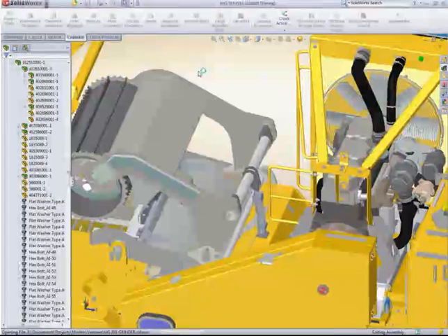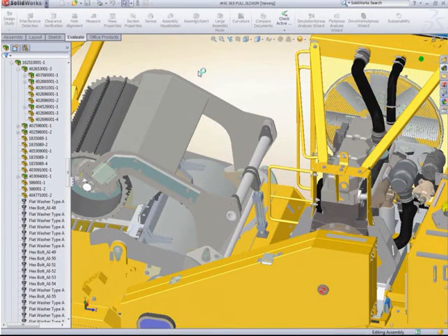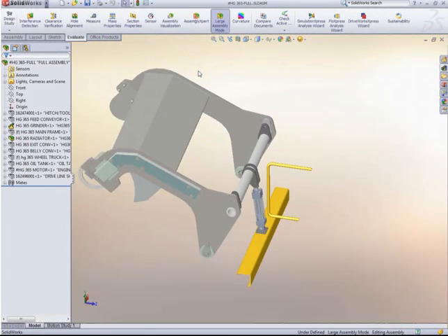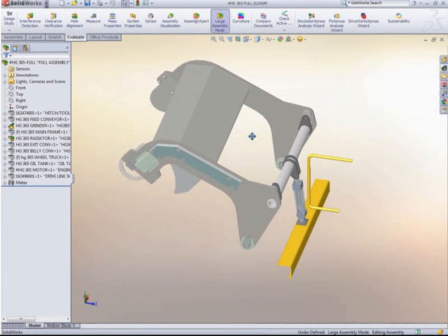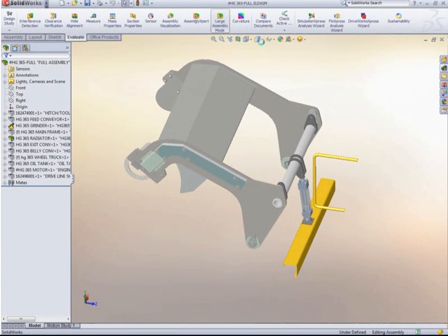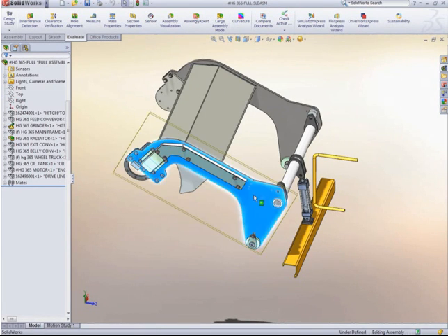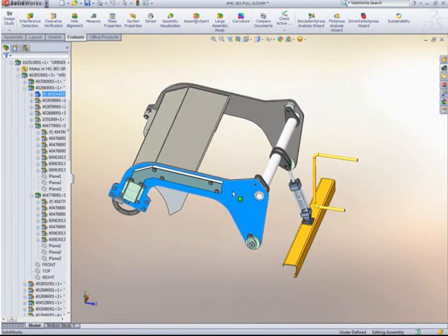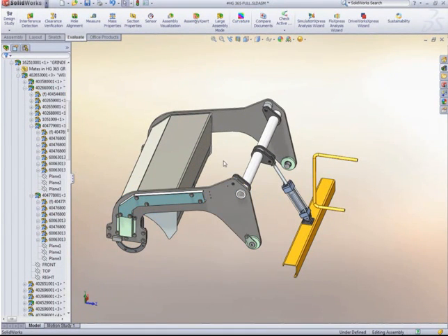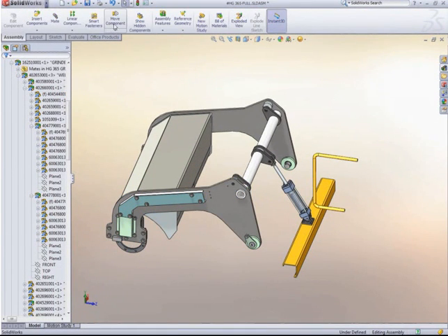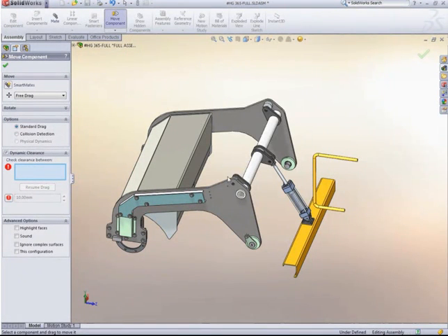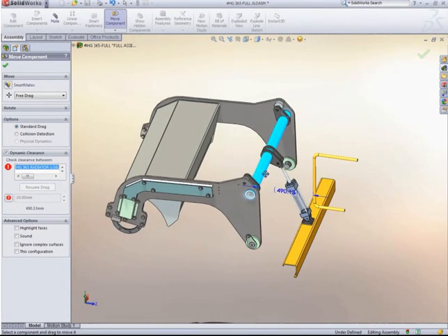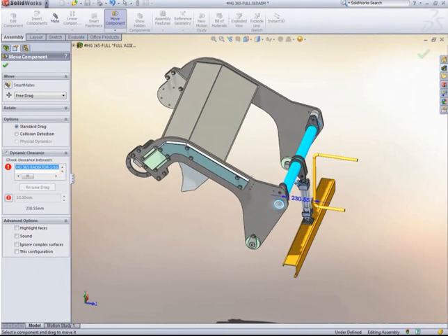Once we're satisfied we have everything we need, SolidWorks opens just those parts and leaves everything else hidden. What's amazing about this way of working is that even though we haven't loaded any of the parts that these components are assembled to, SolidWorks remembers how they were put together and allows us to test any moving parts, or use any of the other assembly design tools like the hole alignment check or interference detection, or in this case, check that the operator won't get his hands trapped by checking the clearance between two parts.